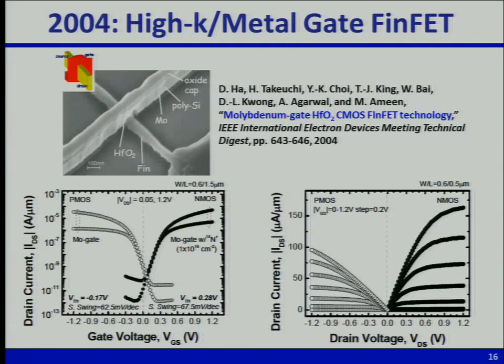How do you adjust the threshold voltage of a 3D transistor? I mean, how do we do it for a conventional transistor? Ion implantation in the channel. Now, ideally, though, for a FinFET, we don't want to implant any dopants in the channel. I guess I can explain why, but just take that for now. We cannot really easily adjust the threshold voltage by changing the doping in the fin.